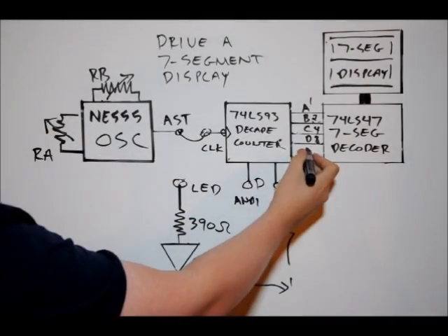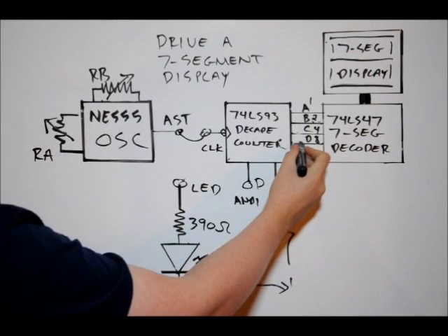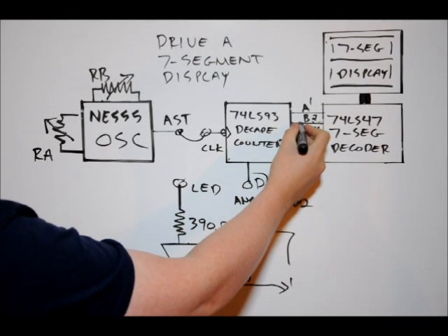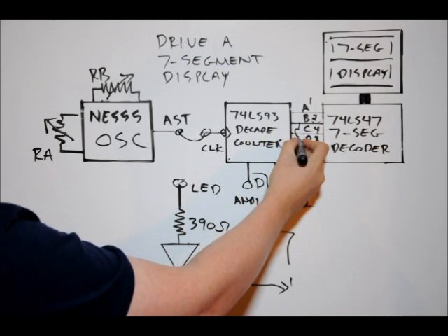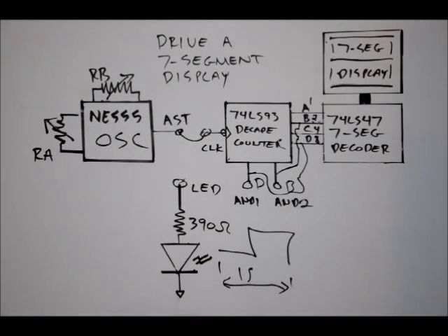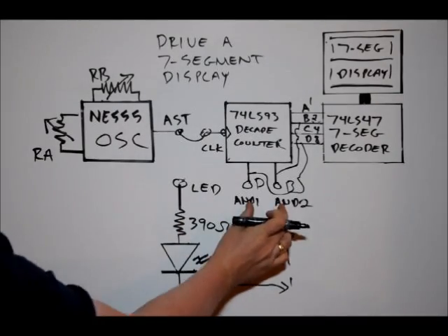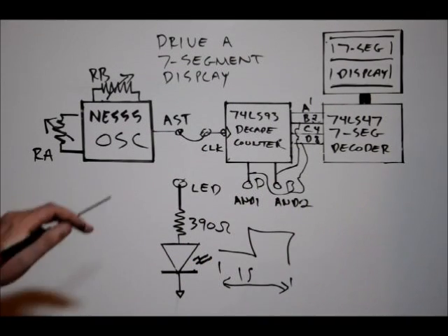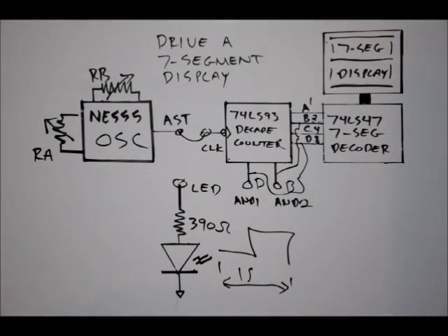So what we have to do is connect D to one of these lines, and B to another one of these lines. It doesn't matter which one. It's an AND gate. If both of these lines are high, there's an instant reset on the 74LS93. Hopefully that makes sense. It'll make more sense if you watch the tutorials. I hate to keep pushing the tutorials below, but they're very important for you to understand the theory behind the learning board. It's very practical.